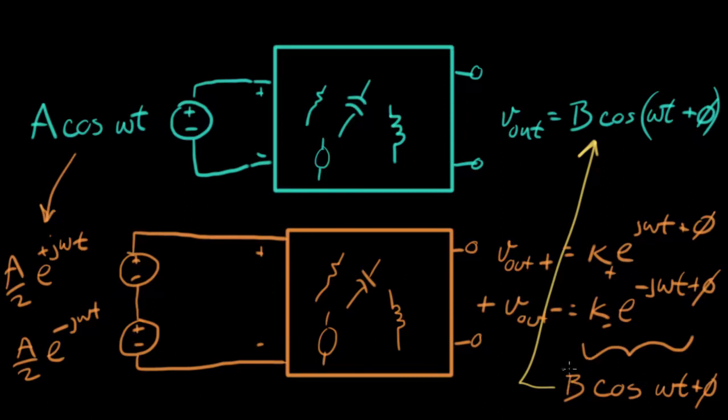So that you know it's not twice as much work, it's going to turn out that this whole solution down here using the negative exponential is going to be exactly the same as the positive exponential, except there's this complex conjugate in here. So for real signals going in, these answers are always complex conjugates of each other as long as we start with a real input. Okay, so that was a review of Euler's equation and a little sneak preview of how we're going to do AC analysis using this really powerful tool.